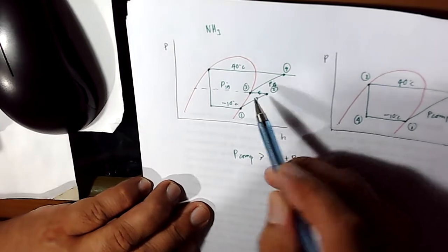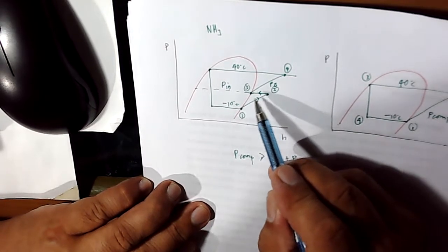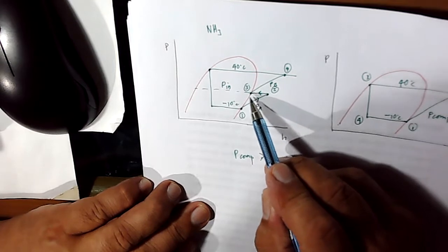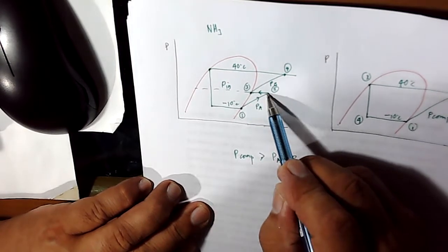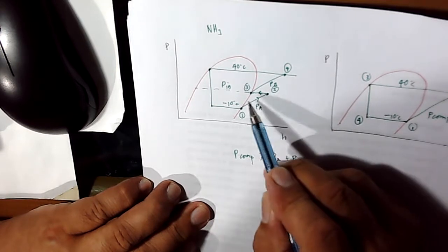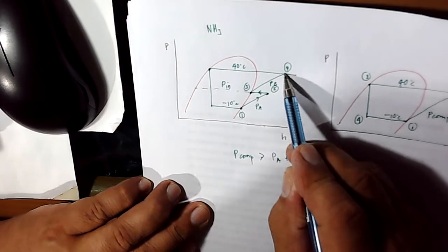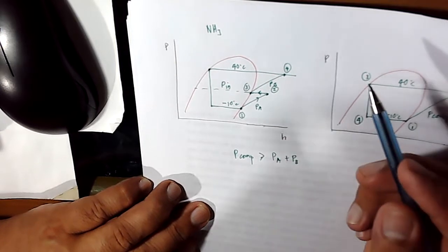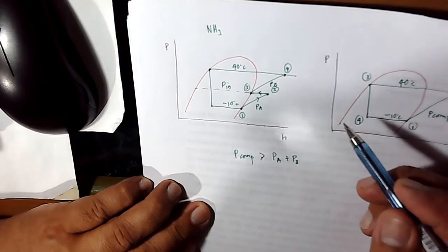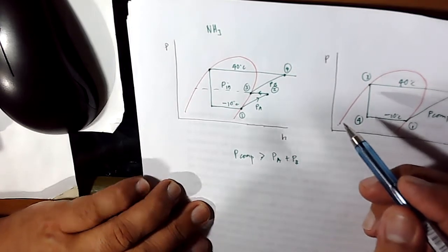Thereby, the cooling water absorbs the heat on the refrigerant side and changes the superheated vapor to saturated vapor before the complete compression in the second stage, or the higher stage compressor. That is by the use of intercooling with a water-cooled heat exchanger.